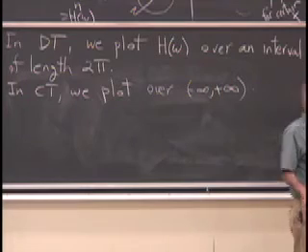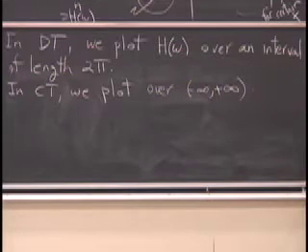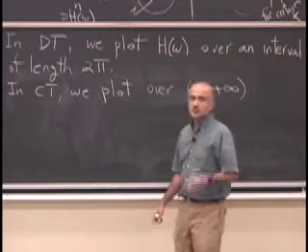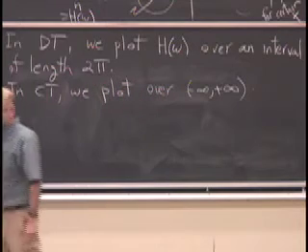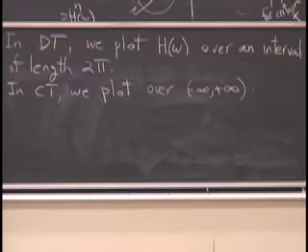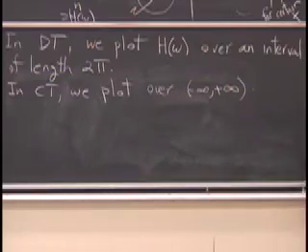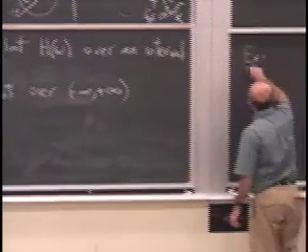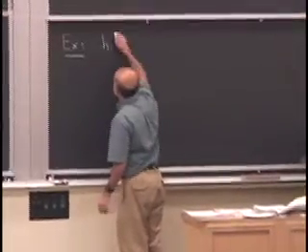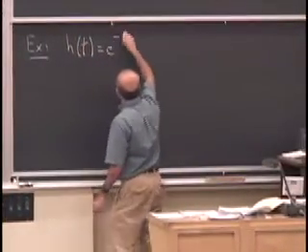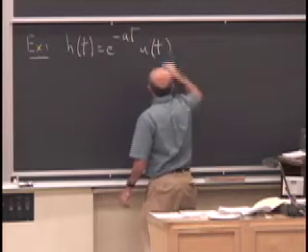Now, these distinctions aside, I want you to constantly be aware of the parallelism between continuous time and discrete time. Very often, all you have to do is convert a summation to an integral, and pretty much the relationships will hold. Use that to your advantage, so you have to memorize less. Let's do an example. Suppose I have a filter whose impulse response is e to the minus a t u of t.